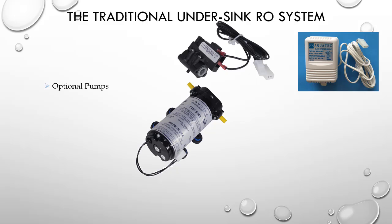They aid in speed of production. They help achieve higher quality permeate water and higher storage tank pressure. The booster pump you see here is typically used to feed incoming water into the RO system when the TDS is high. I personally recommend a booster pump on TDS over 700 parts per million or milligrams per liter. Parts per million and milligrams per liter, for all intents and purposes, are the same amount.